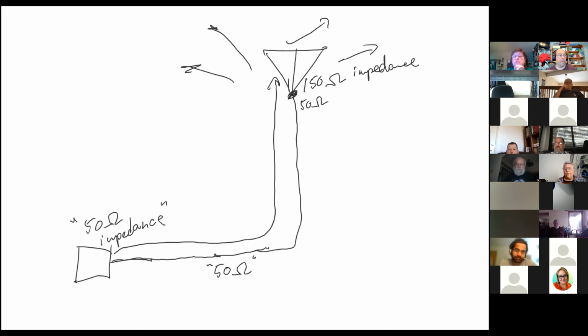Well, ideally, what if the jump rope were infinitely long? What would happen? It would just keep going forward. It just won't reflect. It would go forever, right? So what we're looking for is an impedance match that would basically be the equivalent of a jump rope that went on forever. Well, we don't have that. We have this mismatch. It's tied to a doorknob, which means that our signal will go out and then some of it will be reflected back. Well, if some of it is reflected back, where does it end up?